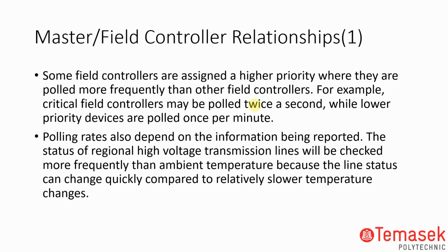You can poll twice a second, or the slower devices can poll once a minute. They're just polling them and asking, do you want to respond or not? Whenever they are doing this, the rest doesn't run, so let's just run that particular portion. That's where the interrupt comes in.